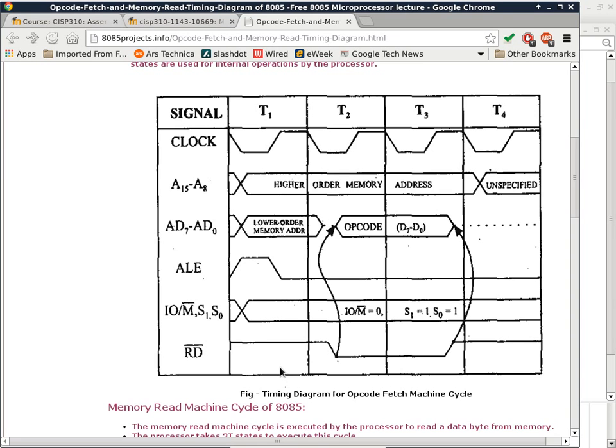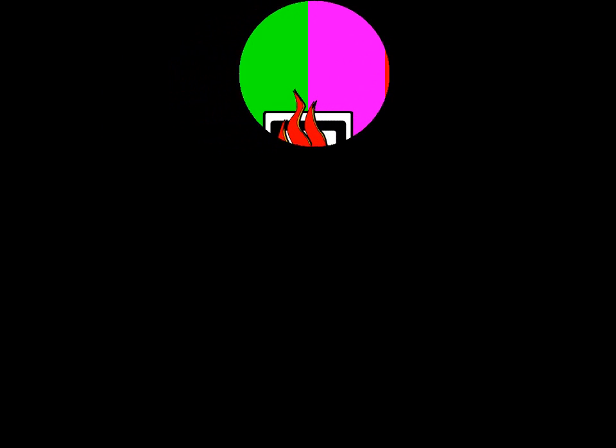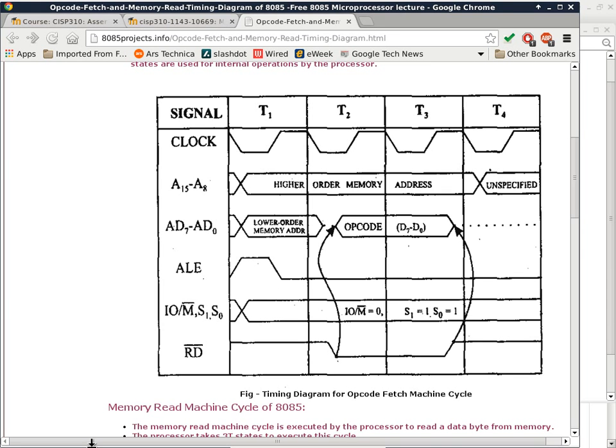Now there's a different modified architecture called the Harvard architecture. Has anyone heard of the Harvard architecture? It is slightly different, but it makes all the difference. It basically says we have one pair of buses, a data bus and an address bus, for instructions, and a different pair of buses for data. So now there's no contention, because to fetch your instruction you'll be using one bus, but to get data or to store data, you're using the other bus. And just because of that, they can improve the throughput quite a bit.